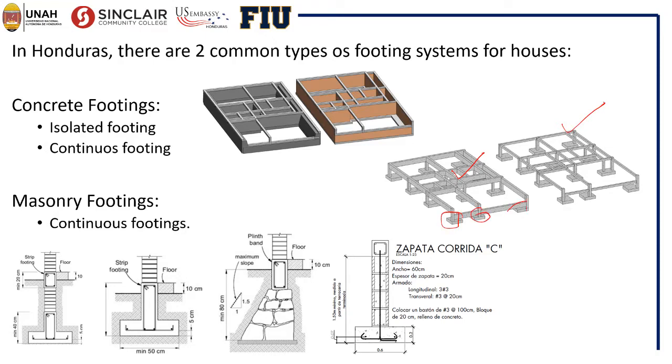As you can see, it's a kind of pad on the soil that is in charge of transmitting the load carried by the column and transmitting that force to the soil, distributing it over a wider area. And to connect all the isolated footings, we have these beams or foundation beams that, especially in Honduras, we call solera.